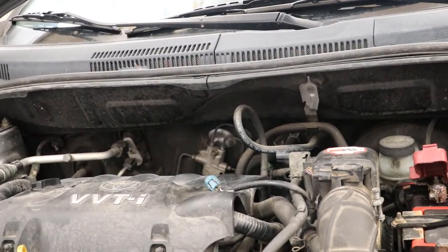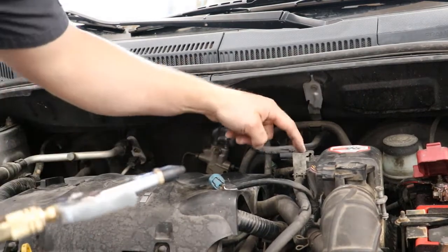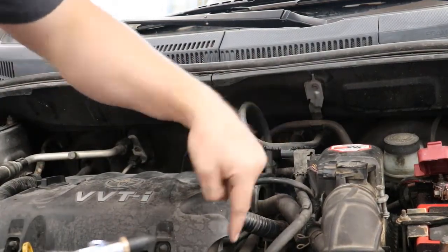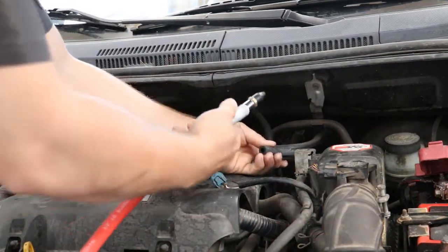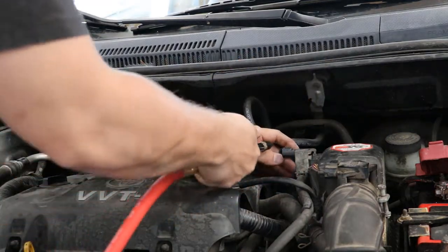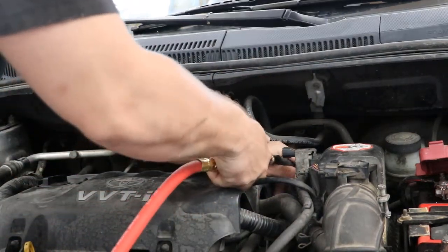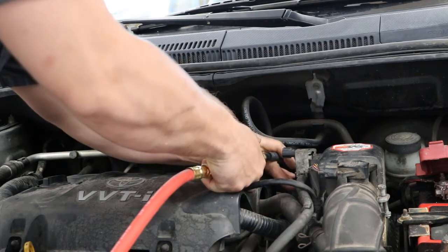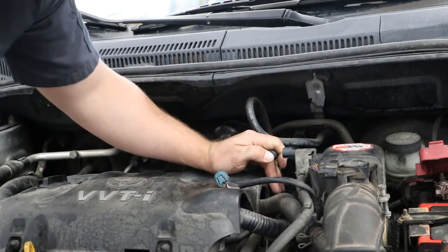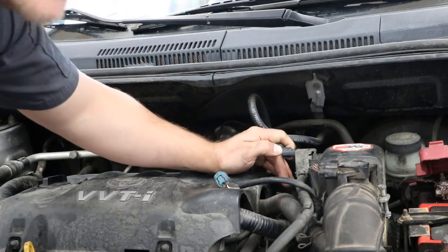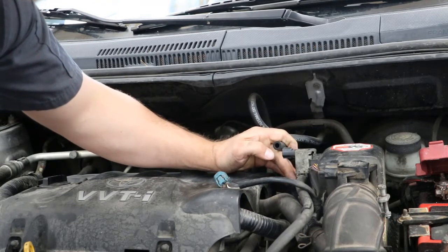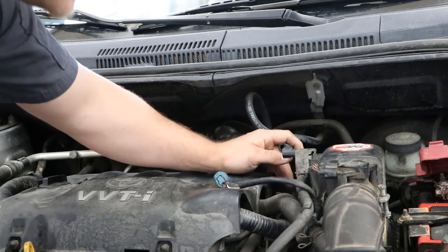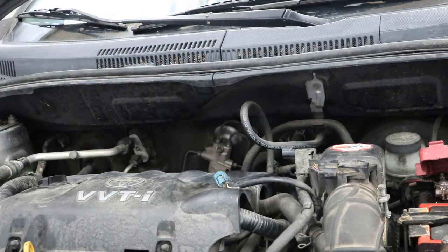So the back part of the valve here, there's the one that goes back to the gas tank, and there's the one that goes to the manifold, which is where the vacuum comes from. So what I'm going to do is put the tip of this just into here, and put a little bit of pressure. And I'm going to hold it with my thumb. A good test as well is just to release and see if it holds pressure. I don't know if you guys heard the hiss. It is holding pressure. So now I'm going to put pressure on the system.